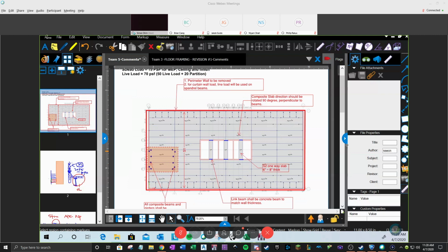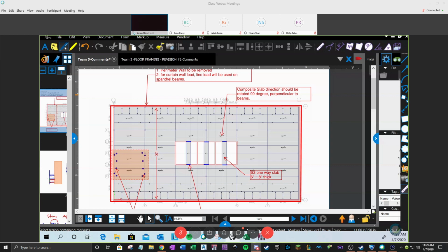It seems like you guys understand that moment release. So I think beam orientation first, and beam ends. When you address the beam ends, understand clearly that it depends on your floor system, your design intent. But typically, once we choose just gravity framing, all beam ends have to be moment released. So I think you guys already understand this.